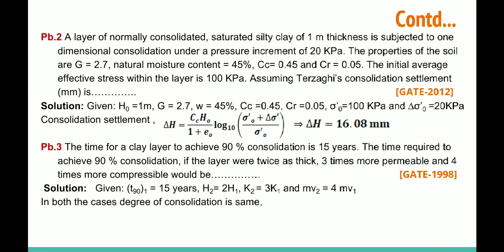So in both the cases, the degree of consolidation is the same. When the degree of consolidation is the same, we can say the time factor would be the same, because the time factor depends only on the degree of consolidation. So we can take the time factor and equate both the stages.